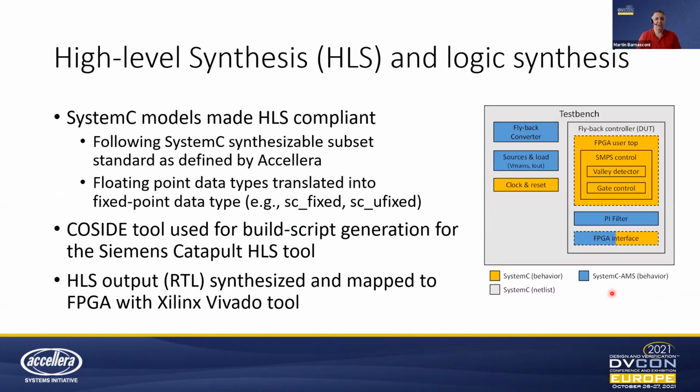High-level synthesis and logic synthesis is used for the digital blocks. I already mentioned that, and the exercise there is that when the SystemC models are developed at a higher abstraction level, we need to make sure they can be synthesized following the Accellera synthesizable subset, using the correct syntax, as well as moving from floating point to fixed point notation, obviously.